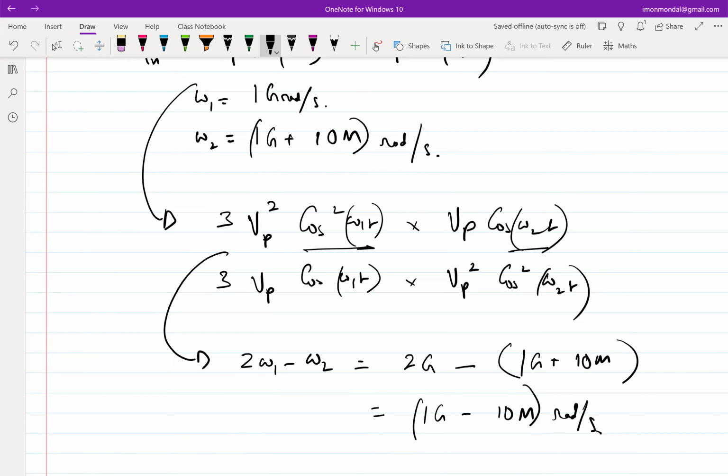Right? So in the next class, what we'll see is what is the effect of this distortion component and how do we characterize it. Okay. So that's another crucial aspect of why RF design metrics are sometimes different, because when you are doing analog design and you want to find out harmonic distortion, you generally tend to put an input. If the bandwidth of your amplifier is 10 megahertz, you put a distortion component at 3 megahertz, assuming that the third order will be at 9 megahertz, and you find out the strength of that. That's fine. That is accepted.